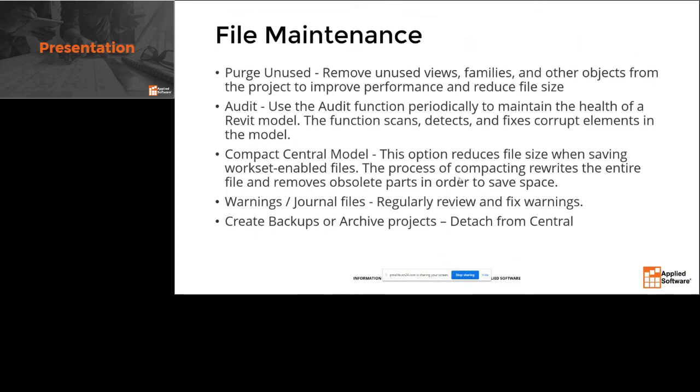So if you guys have users that are old school like me, I come from the old AutoCAD days, back in release 9, we double clicked through Windows File Explorer to open up our CAD files. That's a no-no, that's not acceptable in the Revit world, right? Not even with AutoCAD anymore. You can't even double click on AutoCAD files, or you shouldn't. You should be using the open command. And in the open command is really the only place you can audit a model. So you can't do that any other place.